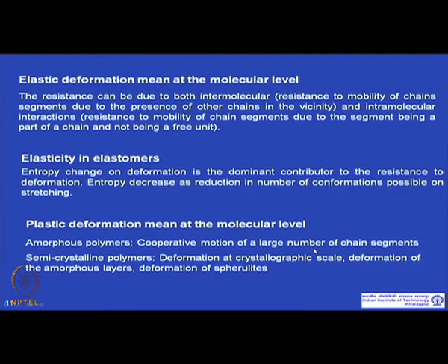Polymer chains might slip in the direction of the applied stress, or move in the perpendicular direction, and there could also be deformation in the amorphous region, or in the spherulite region.